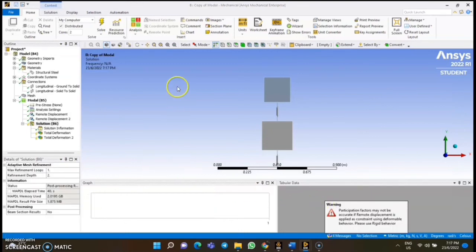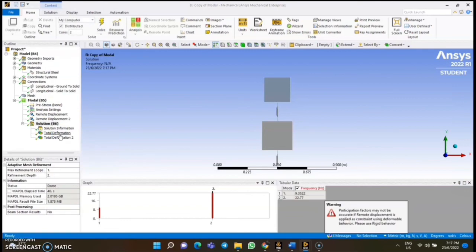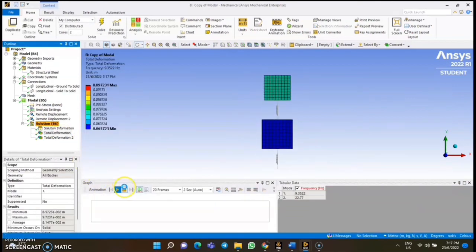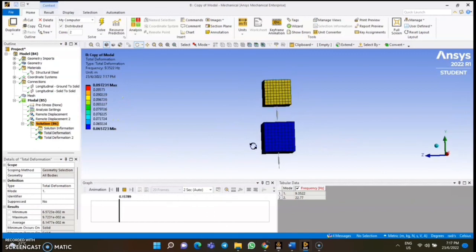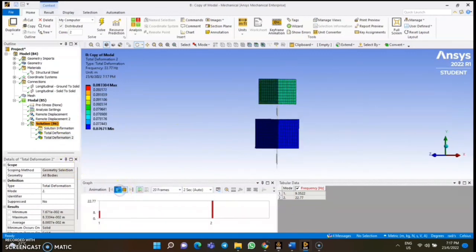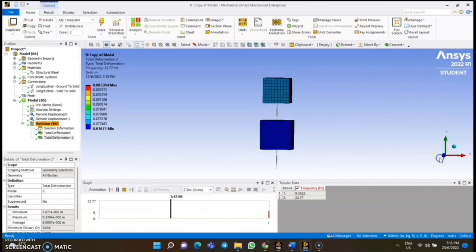So we can compare that the values of natural frequency that we get from the theoretical calculation and by using the software are slightly different. So here is the mode shape. We can see that masses M1 and M2 are moving in the same direction. For the second natural frequency, masses M1 and M2 are moving in opposite directions.